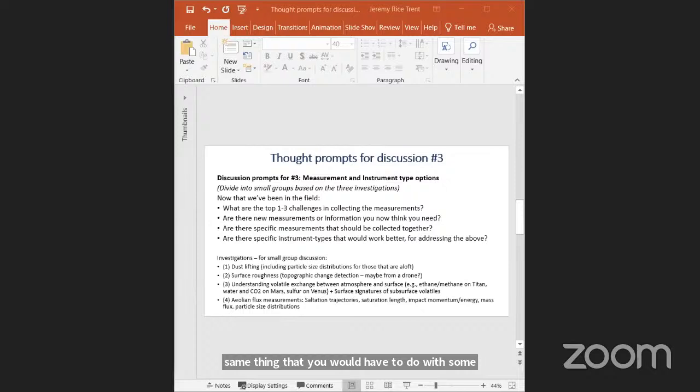But one advantage of taking the geometric measurements is that the errors associated with those measurements are well known, whereas any measurement errors and the propagation of those errors from the aerodynamic measurements are relatively large and less well known. And so there were considerable advantages associated with using a geometric measurement, however that may be done, over the aerodynamic one for those reasons.